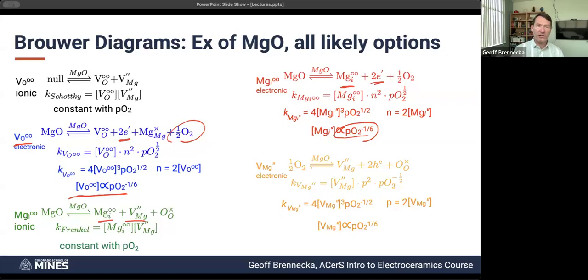Magnesium vacancy. So you notice in here, I've got oxygen vacancy, ionically and electronically compensated. Magnesium vacancy, ionically and electronically compensated. Magnesium vacancy, ionically compensated, we already covered that right there. It's just a Schottky. And the one that I left out of the stoichiometric or simple defects would be the oxygen interstitial, and that's because we've just said that it's highly energetic, highly costly.